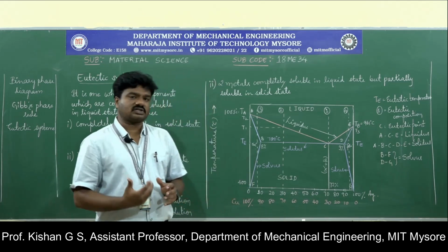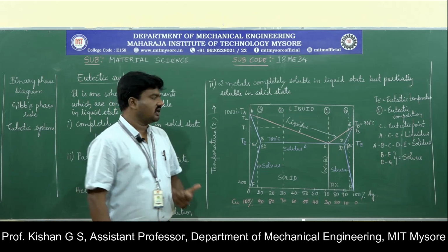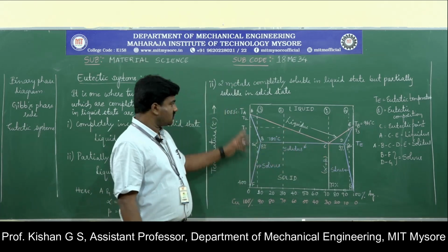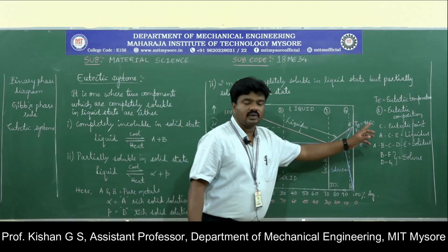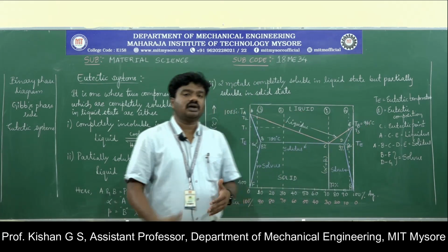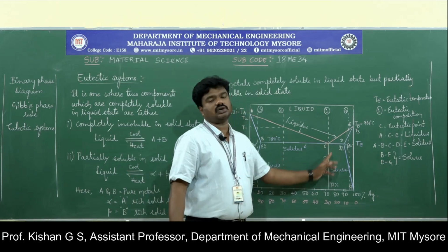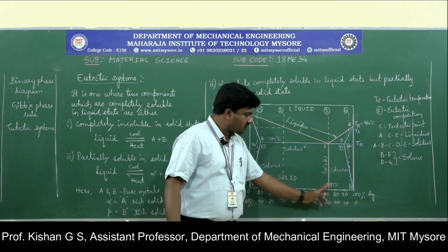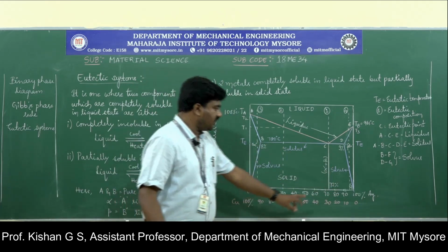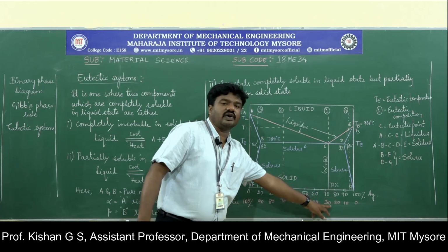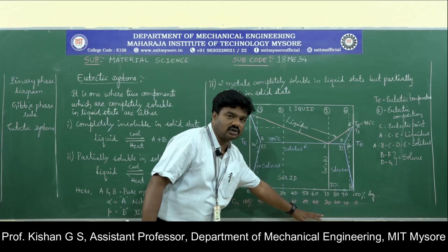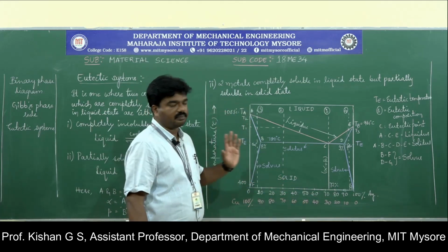So now for the purpose of understanding, we can take any letters for representation. Here we have considered the point C, wherein both the metals, that is copper and silver, under the solidification process come and meet at a particular point, and that particular point satisfies the eutectic point. The composition at the eutectic point is 72% of silver and 28% of copper. You can observe the composition here. Along the x-axis it is the composition, along the y-axis it is the temperature.